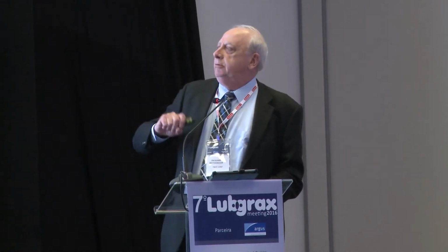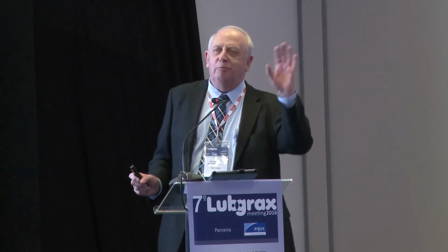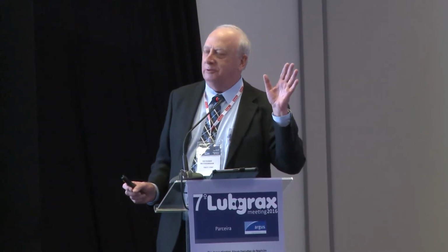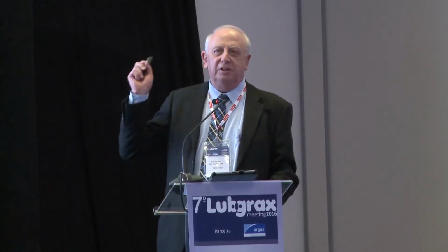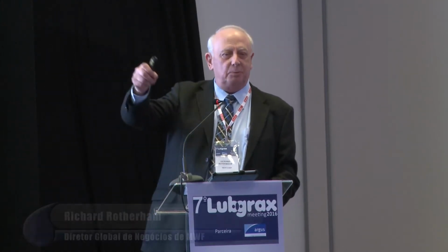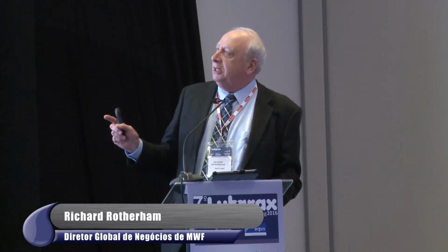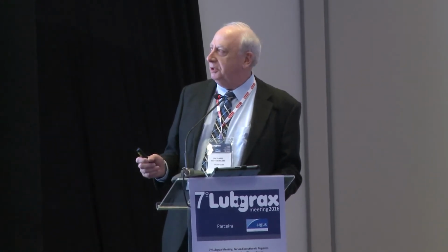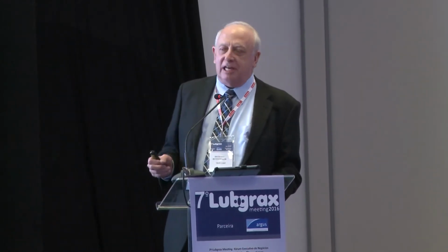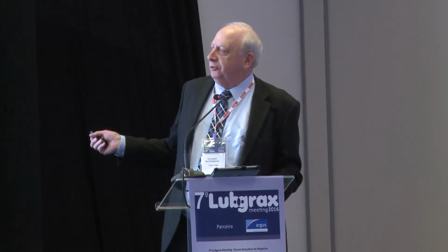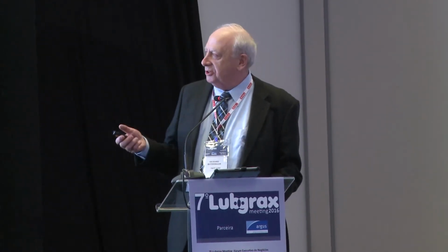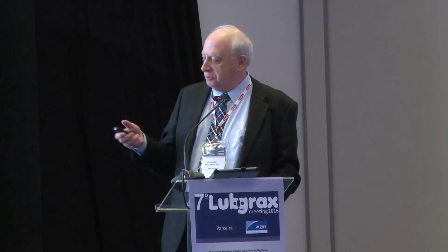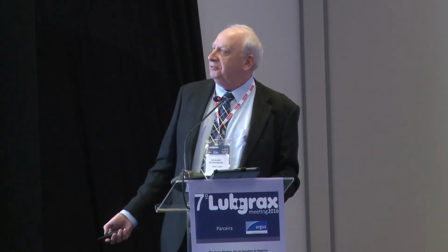Importantly, I know the real world doesn't always allow you to start off with a clean system. Often, when you get a new customer, you have to go in on top of the old fluid. But the reality is, if you really want to get good control, you need to start off with a clean system. So add a system cleaner and a full dose of biocide at the start of the last shift before dumping the old system. Physically remove any contamination on system surfaces, and then rinse the system, ideally with a solution of fresh metalworking fluid, or at least with clean water before charging with fresh fluid.